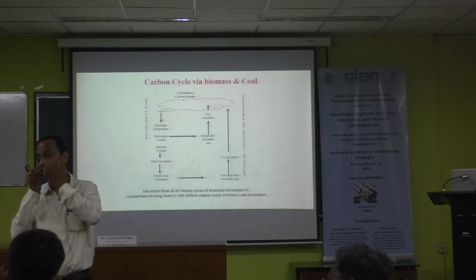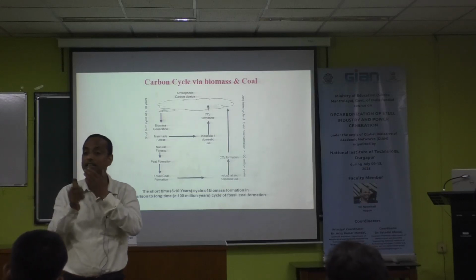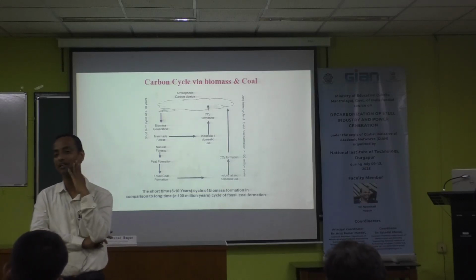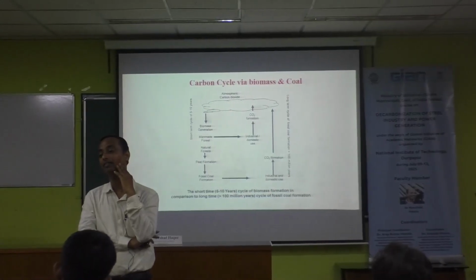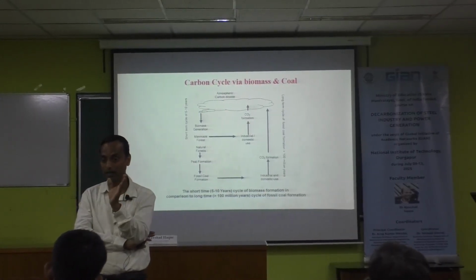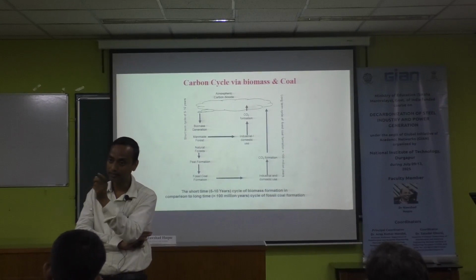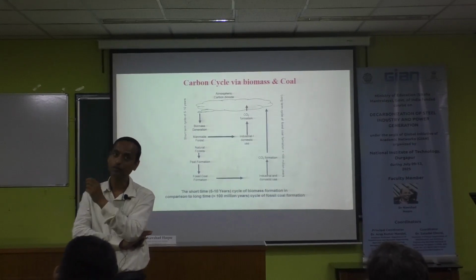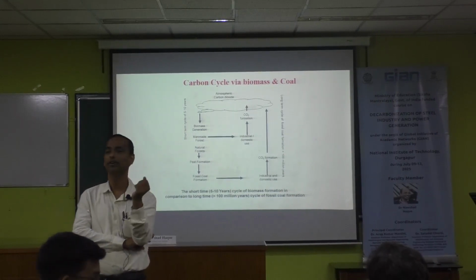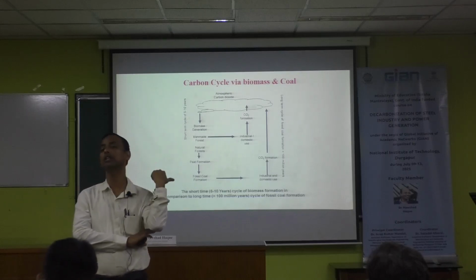Fe total means after reduction only you get 70%, 80% metallization. But if you see any other DRI, it will go up to almost 80-85%. It is less due to the coating here.